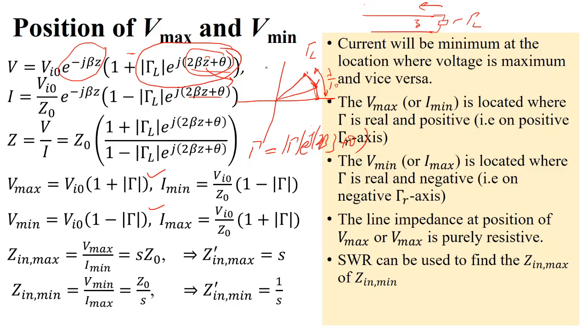If you see the Smith chart, you find this lambda, which means you are moving lambda by 10 here, and you will get the maximum voltage. So the maximum voltage will occur on this line. But you have to find the initial reflection coefficient at the load and how much lambda you have to move to reach this point. The maximum always occurs when this gamma comes to the positive real axis of this plane. Similarly, for the minimum voltage, this phase has to be minus pi.